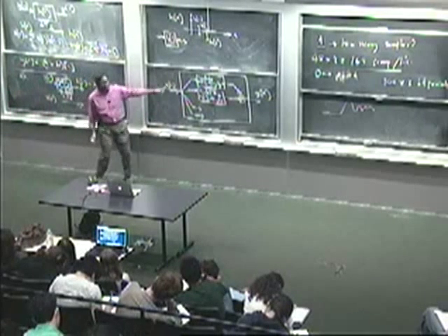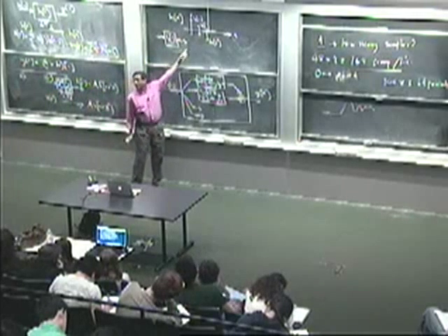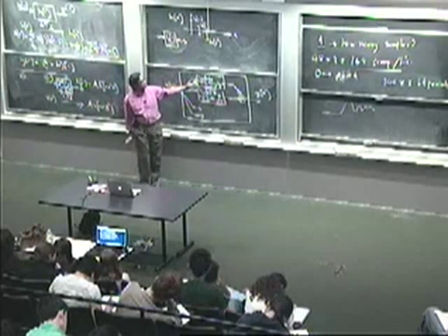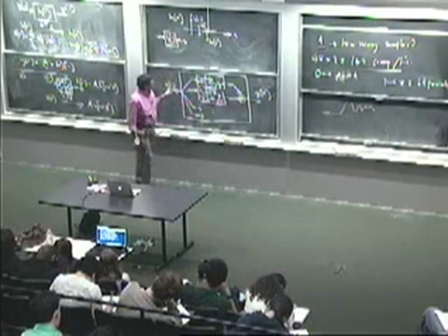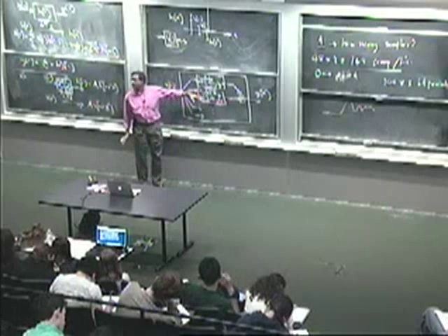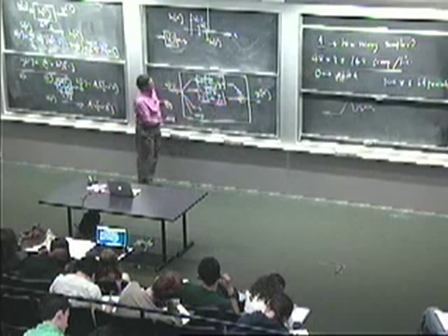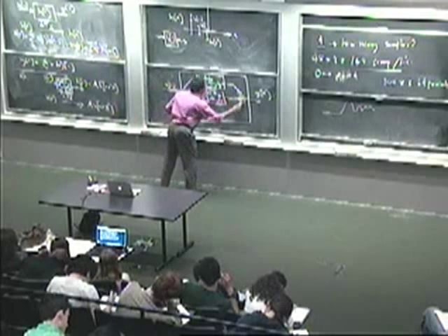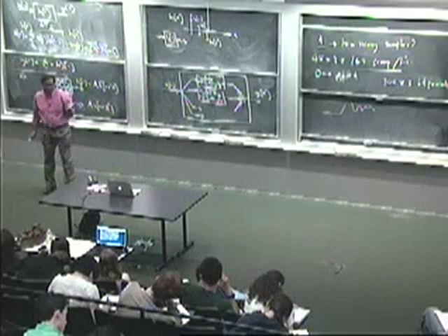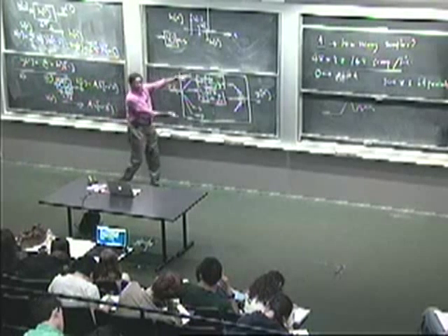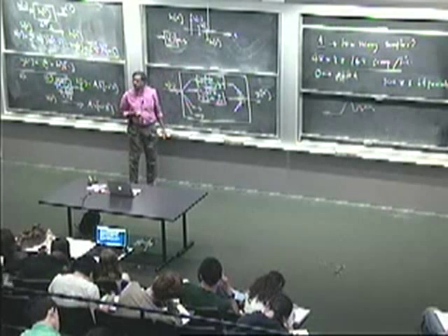If I put a unit sample in here, what comes out? It's going to be exactly that, right? Because the unit sample would get scaled by h0, delayed by nothing, and come out there. The unit sample will get through this path, scaled by h1, delayed by 1, come out there. When you assemble all of these with this summer here, you're going to get exactly that response. So here's another way to think about what's sitting inside an LTI system whose unit sample response is given to be that. Okay?